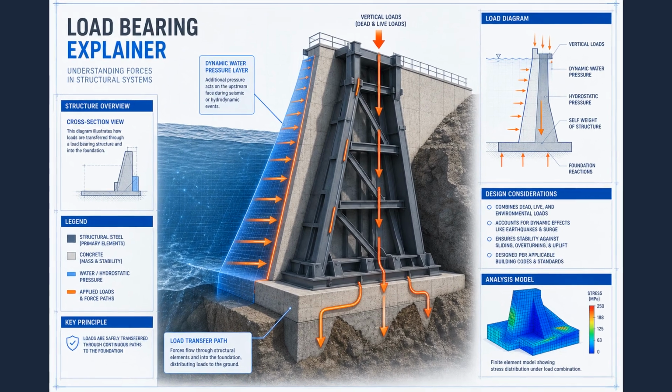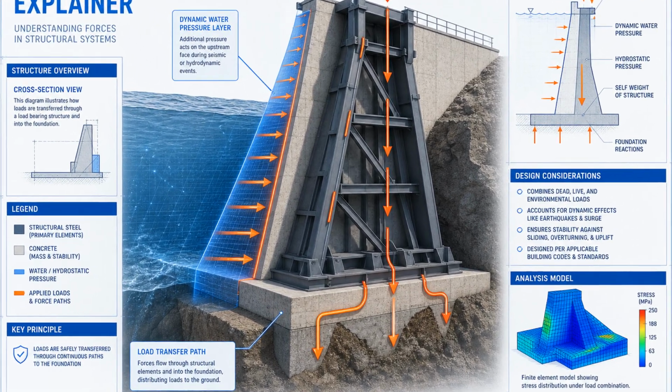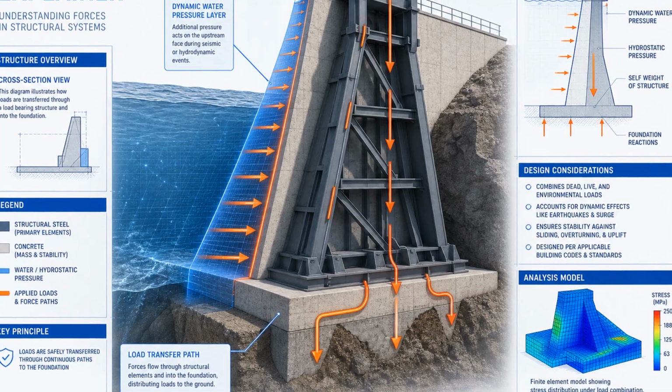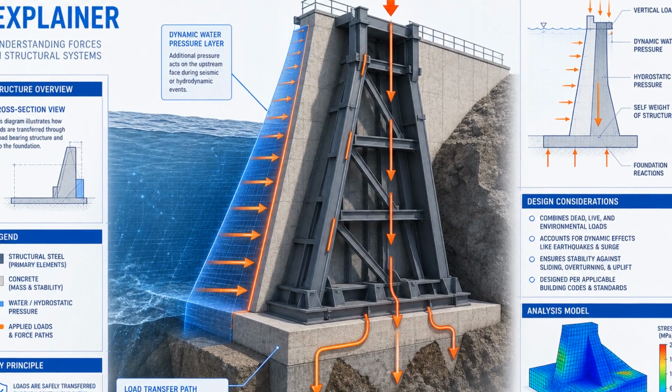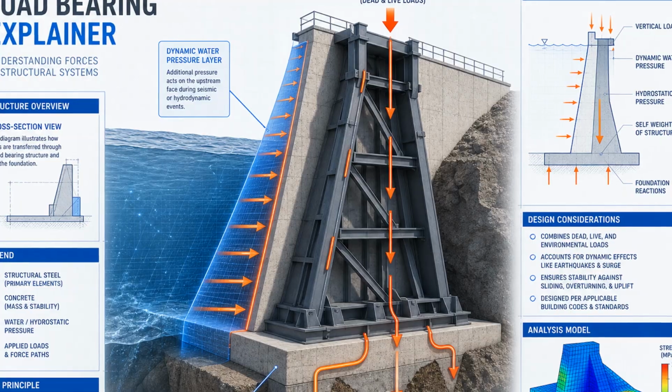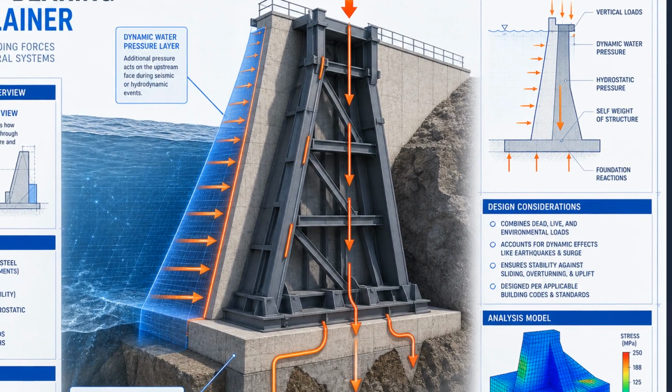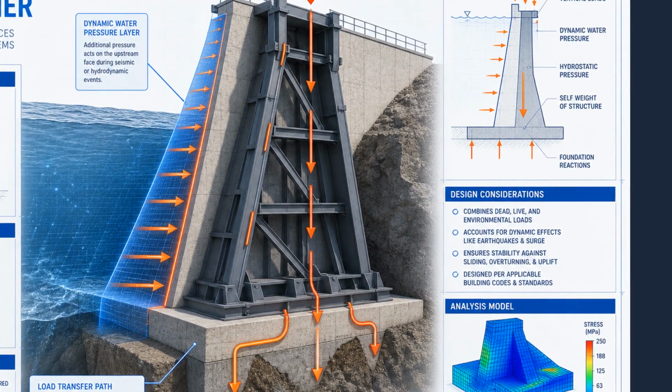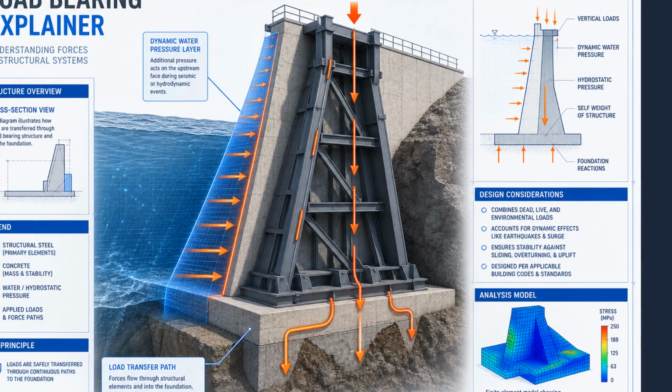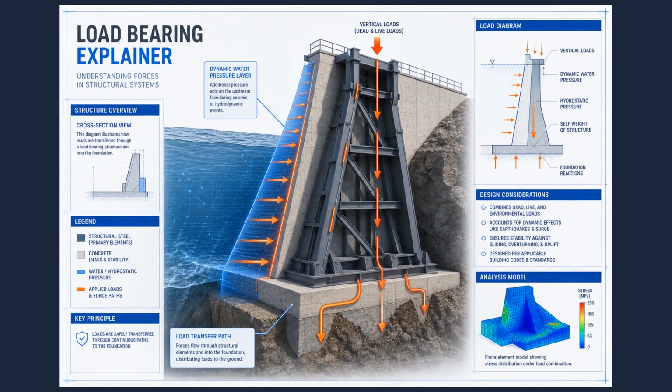In seismic regions, dams are checked for earthquake-induced inertia and hydrodynamic pressure. Models simulate dam, reservoir, and foundation interaction so movement stays within acceptable limits and critical sections maintain capacity.